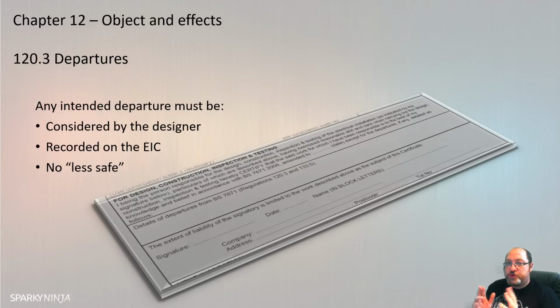We may choose to carry out some inspections or some tests to determine the effectiveness of the insulations, the conductors, continuity and resistance measurements, just to get an understanding of how it's been manufactured. If we conclude it to be safe, just obviously made outside of the country, so not with the same paper trail, if we can conclude that, we may then choose, as long as the client or the architect or ourselves is happy, to bring that in. But as it doesn't comply with Part 5, we'd have to put a departure down in the form there.